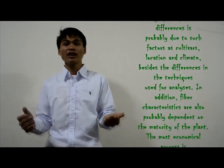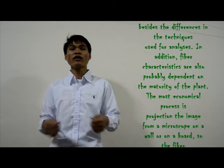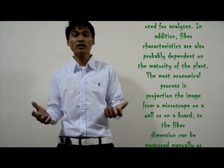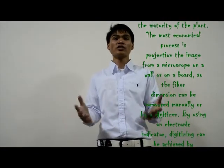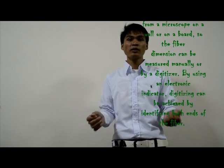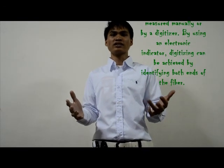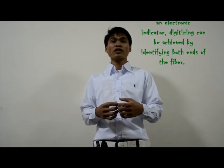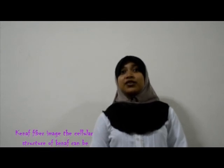Besides the differences in the techniques, other factors are used to analyze. In addition, fiber characteristics are also probably dependent on the maturity of the plant. The most economical process is projecting the image from the microscope on the wall or on a board, so the fiber dimension can be measured manually or by a digitizer. By using an electronic indicator, digitizing can be achieved by identifying both ends of the kenaf fiber. From the fiber image, the cellular structure of kenaf can be separated using the maceration method.